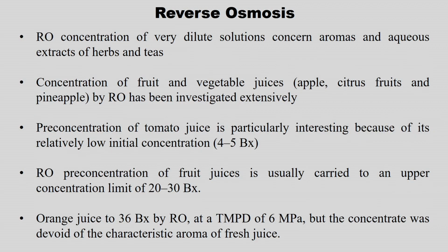So, RO concentration of very dilute solutions concerns aromas and aqueous extracts of herbs and teas. In this case, RO is applied to retain the aromas as well as when we process the extracts of herbs and teas. So, we need to be processing at lower temperature. Okay, so that is why my choice is RO to get the aqueous extracts of herbs and teas.